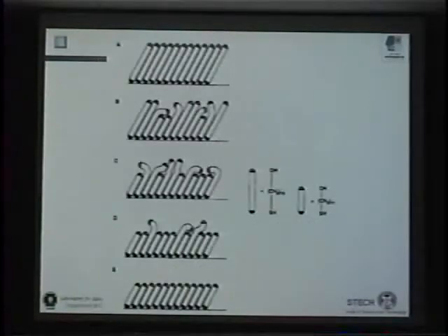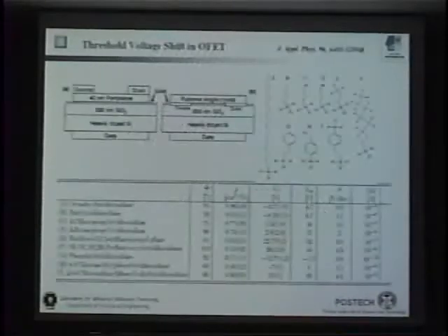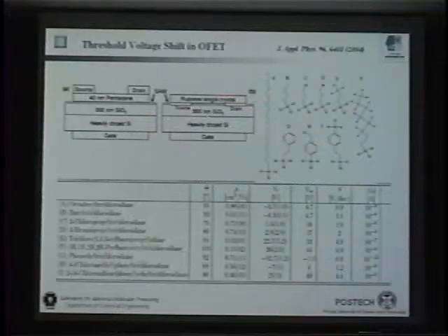Next slide. Sometimes people mix two different SAM molecules, for example one long and the other short. Then you can have all kinds of surface coverage, and the side group will become the surface property. With those kinds of methods, you can play with the surface properties of the film. Next slide. This is a well-known example of treatment of the insulating layer before you deposit pentacene films. Those are the molecules you try, and then you change the mobility and everything.